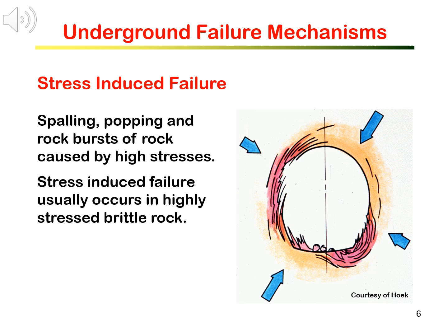High stress is primarily due to high in situ stress associated with great depths or tectonic stress. Localized stress concentration may build up at the corners and at intersections that may become high enough to cause fracturing and breaking of rock at those locations.